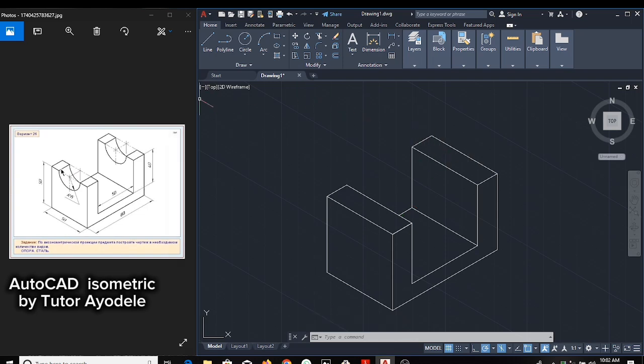So we need to create this circle now, this cut. Okay, so let's do that. What are we given? We're given that the radius is 15. The radius is 15. So what do I need to do? I need to get the center of this 15. So let's get the center. The center should be 25. So let's go on that same line, 25. See? So I go perpendicular 90 degree to that point. I've divided the line into two.